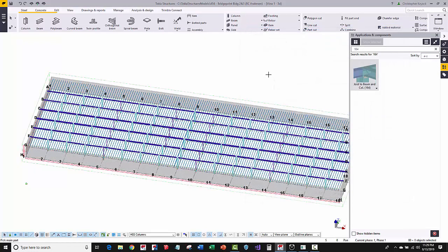Now the out-of-the-box Tekla auto connection doesn't do a really good job of identifying these complex joist connections for multiple members, because identifying the right primaries and secondaries in the right order can get a little bit tricky. And so essentially here what I wanted to do is reduce a lot of the manual input and clicking and get this done really fast, because it's really the same settings used all over, other than maybe changing the cap plate size a little bit, but it's pretty much just getting rid of the tedious action